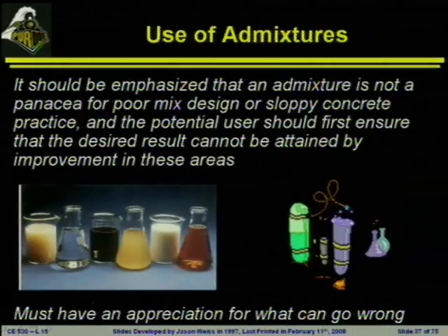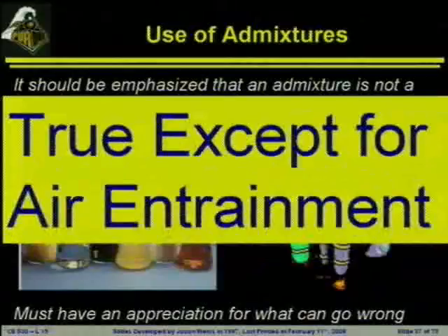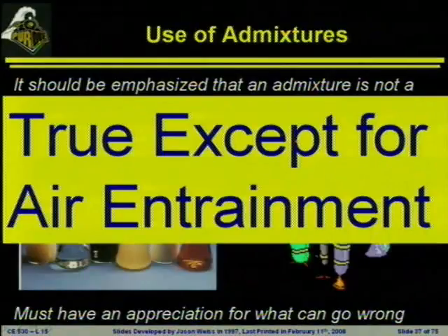free water. Now, one of the things, and I believe this was in our mixture proportioning lecture, I had this fantastic slide that said the following up here, and this is out of ACI. It should be emphasized that an admixture is not a panacea for poor mix design or sloppy concrete, blah, blah, blah. This is really true except for air entrainment. Air entrainment can cure a lot of problems. So you'll see air entrainment coming up quite a bit.